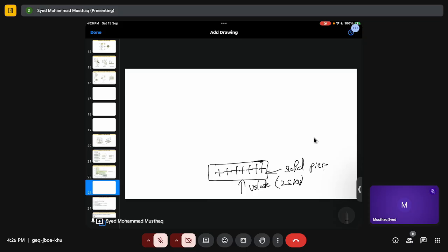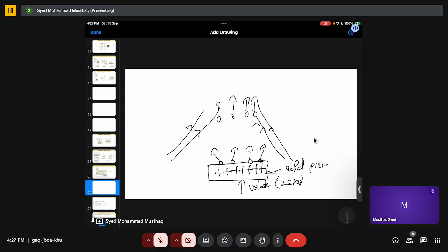Now, because of supplying a very high amount of energy, the atoms will come out. And what I am trying to do is I will purge argon gas here like this, and this argon gas will carry whatever atoms are being taken out, and you have a cold surface, and they get deposited. That's it. That is called sputtering.